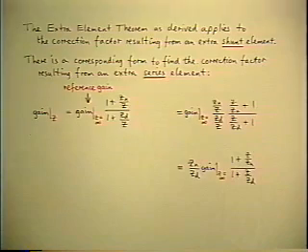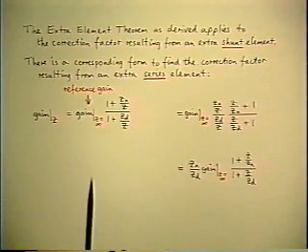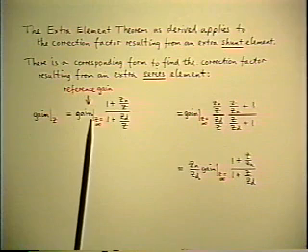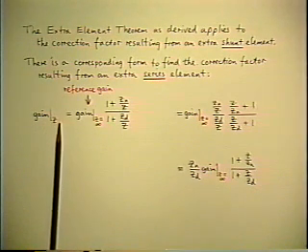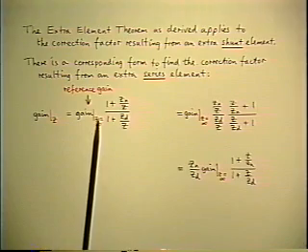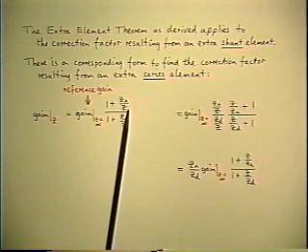So you would expect that there is a dual form of the theorem also. Sort of like Norton's and Thevenin's theorems are duals of each other. And the same is true for a lot of circuit theorems. And it is also true for the extra element theorem. But you don't have to rederive it from scratch. A simple algebraic relationship tells you how to find it. Here's the version we've set up already. The gain of the system in the presence of an element z is equal to the gain when z is infinite multiplied by the correction factor.